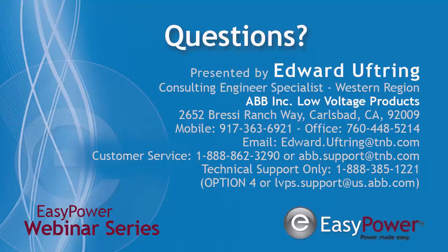The recommended gap between coordinated curves is actually up to the coordination study that you provide. We can go very small. It could be within, I want to say like 0.1 amp, I believe, all the way up to 10 times. So we don't want to recommend what your gap is between the curves, just simply because it depends on how much safety you want to provide into that branch circuit.